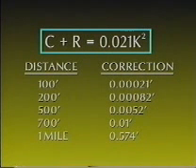C is equal to the curvature correction, R equals the refraction correction, and K is the distance in thousands of feet squared. An example for K would be that if the level line was 2,000 feet long, then K would be 2 squared, or equal to 4. Applying this correction to various sighting distances, we can calculate the combined effects of curvature and refraction.